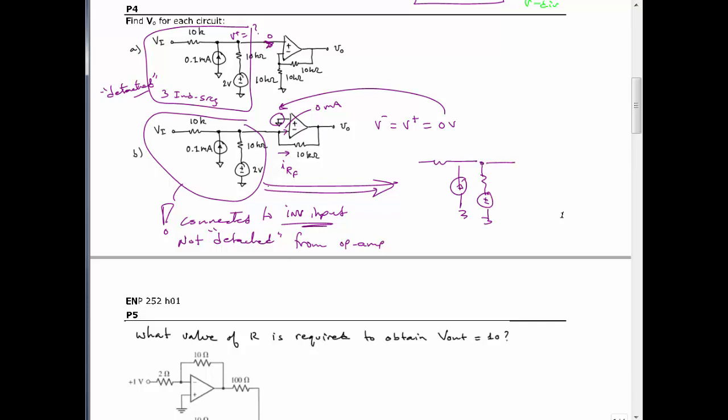Right. But what do we do with this connection that is going over here to the OpAmp? Well, this is where you have to kind of abstract, and there's stuff going on that maybe you don't understand, but if you can accept this reality that for an ideal OpAmp with negative feedback, the inverting and non-inverting inputs have a zero differential voltage, and because the non-inverting is grounded, that means that the inverting, this V minus, is grounded.